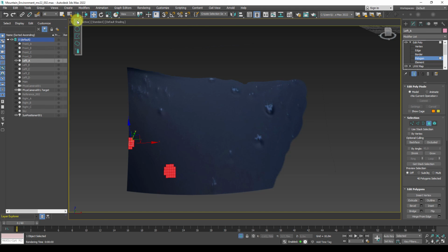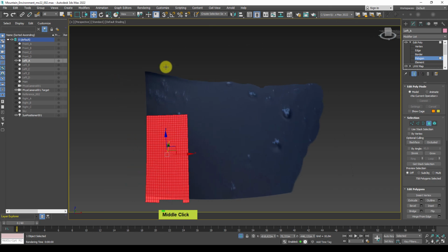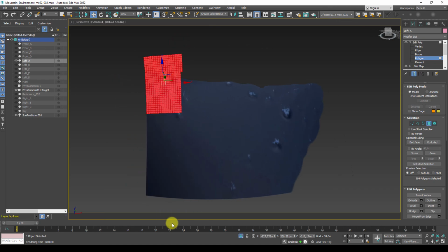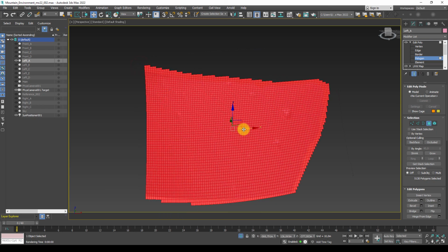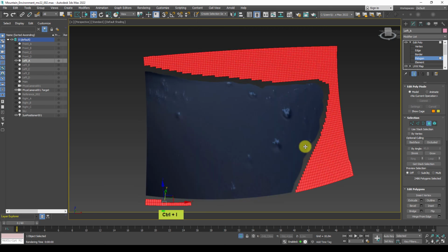So now if I'm dragging my selection, let me show the selection tool. If we hold it down, we have different options to select. So this is the rectangular selection. And of course it's great, but you're somewhat limited in your selection. There's the polygonal lasso, which is also good, so we can go with that. Polygonal lasso, start dragging and tapping and try to select all things. So that's one way to select the polygons, and now we have a selection. We can press Ctrl I to invert selection, and we can hit delete.